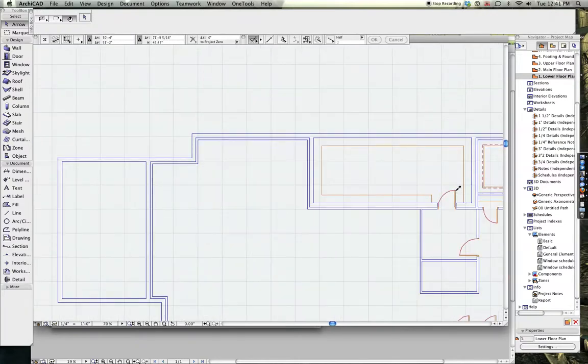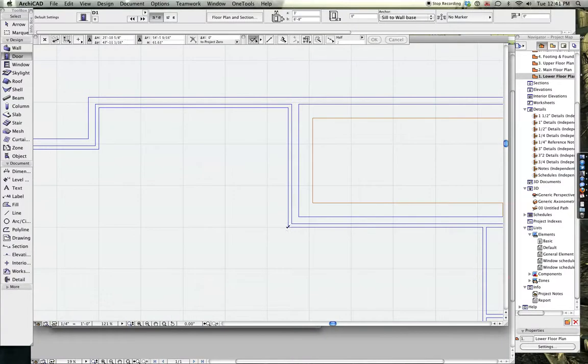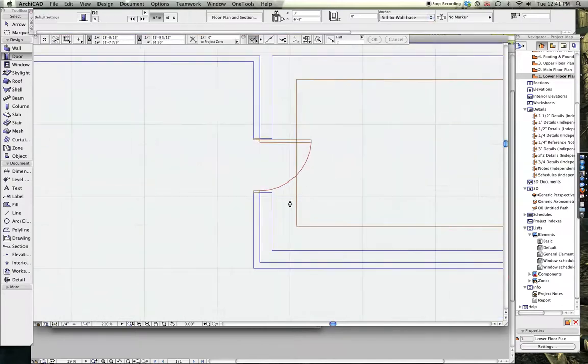There's a door that's going to be over on this side, and we'll just set that in right about there. It's centered in the space just fine, and then we'll make a copy of it, and we'll drop it in there, drag it over so that it's in line, go up to the empty wall opening. There, it's done. And we'll take this line right here, and we'll be on the line tool, so number 4 for the line tool, and hold down the Command button and click the wall to adjust to it.